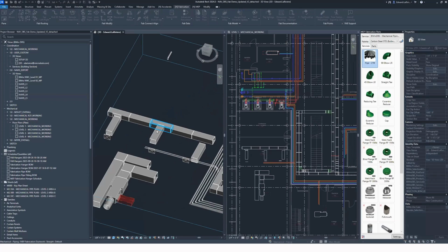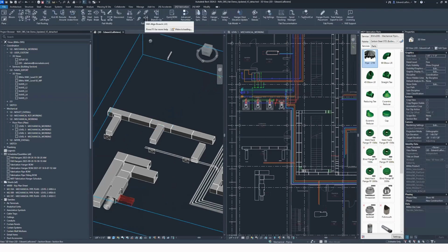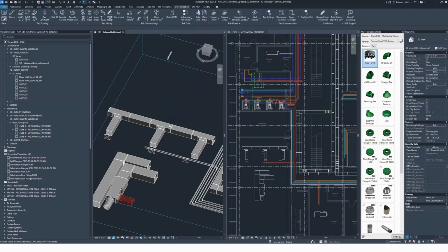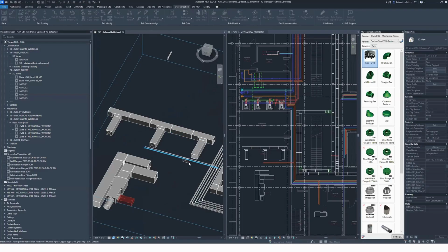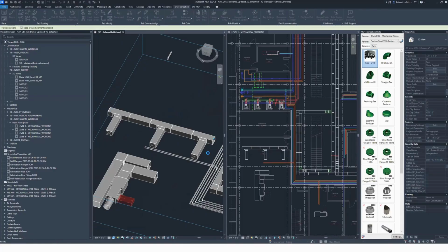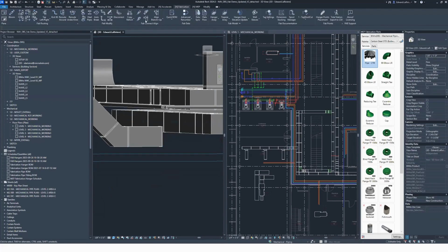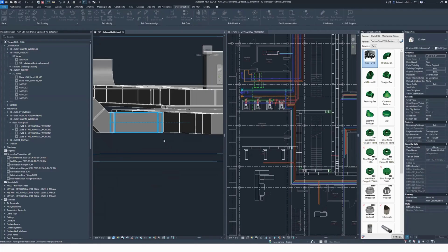We can use those same aligned branches to go ahead and start lining some of these items up. Just locking them into place nice and easy. Use your same trim extends to connect together. Use a tool like Move Connect to go ahead and make it easy to start throwing on some of those terminals at the end of your runs. Use something like the elbow down 45 and maybe pair it with an elbow up 45 to go ahead and get underneath that rack and start connecting into that lower duct. Leverage that same aligned branch for your final tune and a trim extend to connect them together.